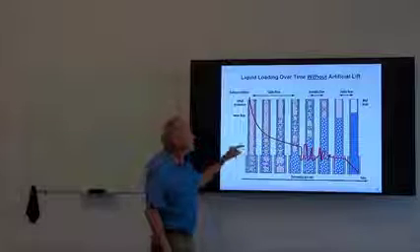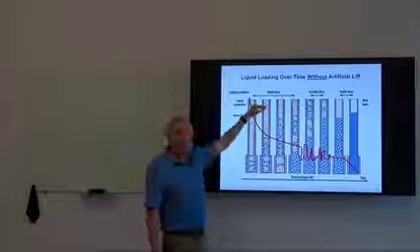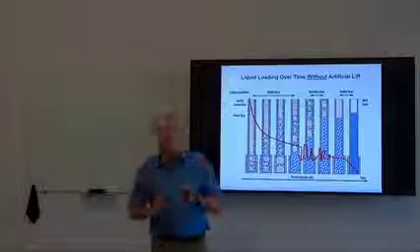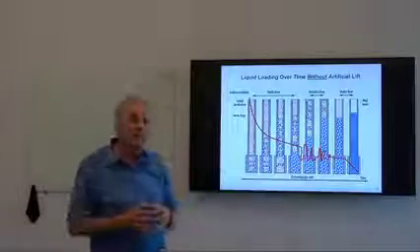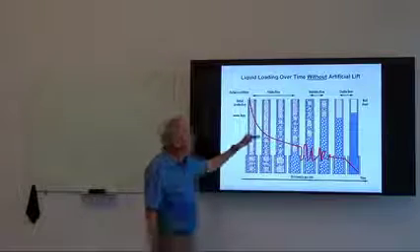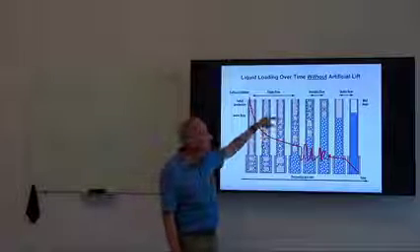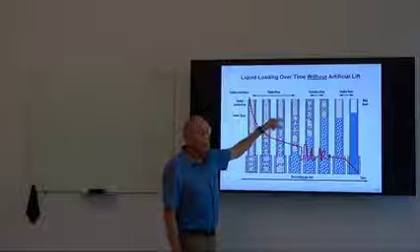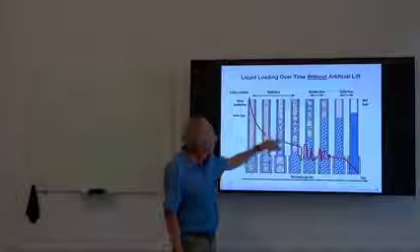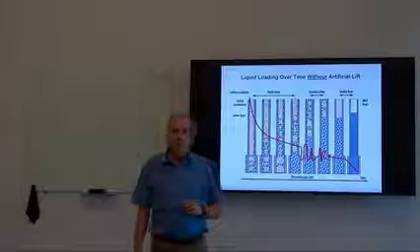Gas velocity, even in this case, is always lower at the bottom of the well than it is higher up in the well. And we reach a transition point, which is some measure of what's called critical rate or critical velocity, a transition point at which there isn't sufficient velocity to lift the liquid. So here we see this is where this transition point takes place. A little later in the life of the well, that transition is up a little bit higher. But we can see that we obviously have a much greater liquid holdup increasing as we have decreasing gas rate.